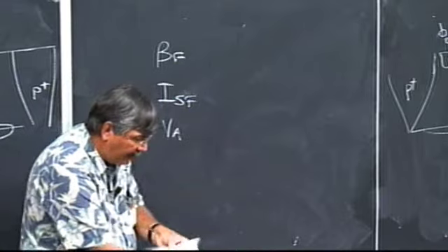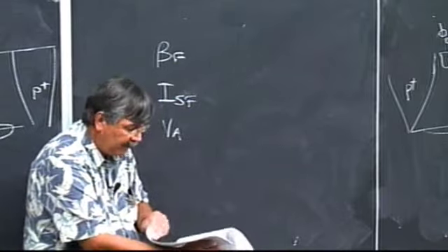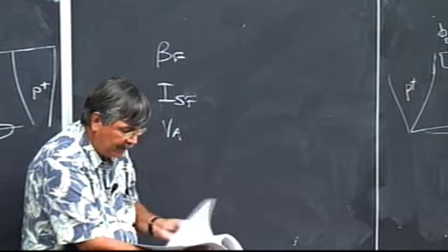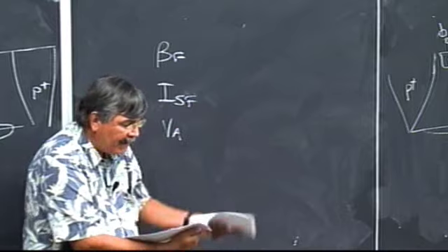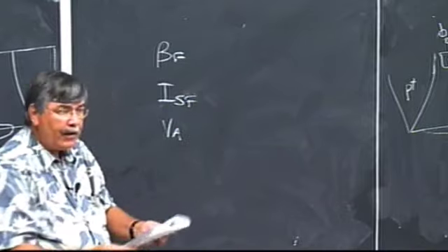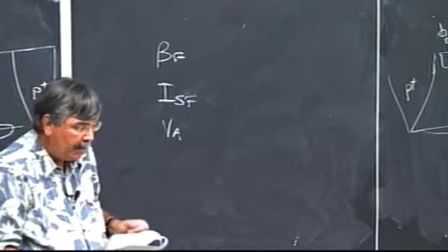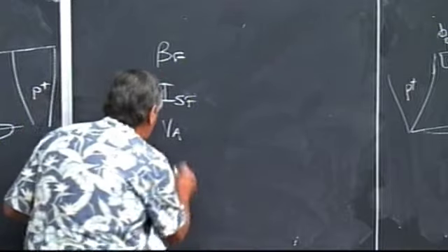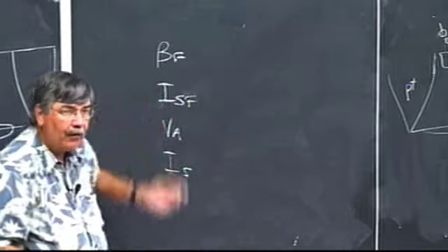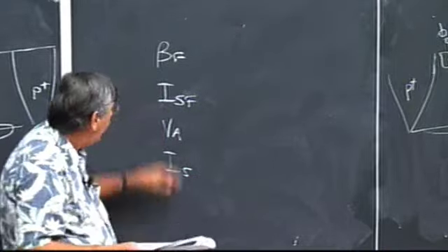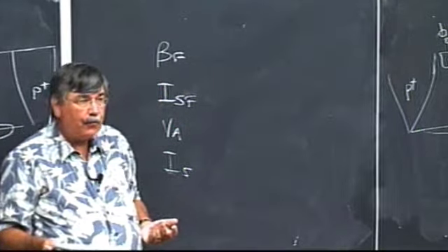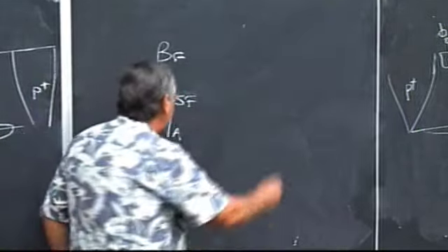So somewhere in the lecture, we're actually up to lecture 5. Maybe I'm too far down the road. No. So in lecture 5, I have a list of the SPICE parameters. And there's about 30 of them in the simple model. So there's a thing called IS. That's the saturation current. Remember, we used that one already. So somebody has to tell us what a typical value is. We have beta, and it's pretty much the value that we're going to use for beta. There's one in the forward direction.